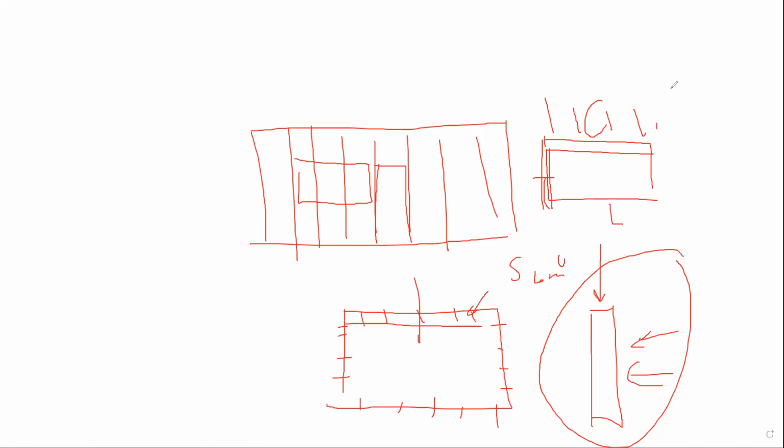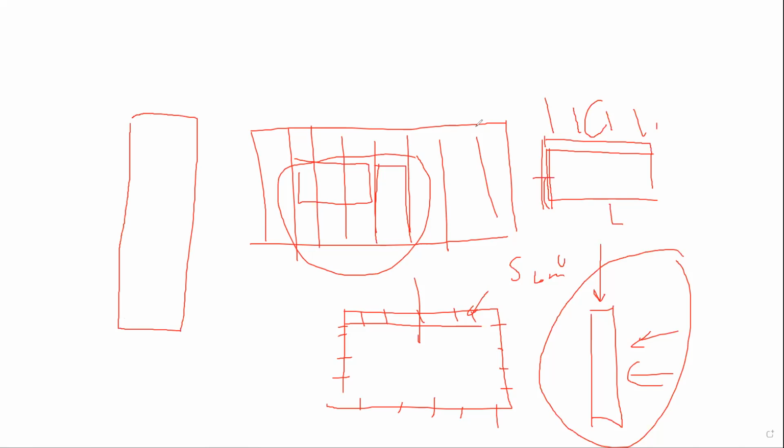So do you understand what that sketch is all about? It's a continuation of the design of an exterior wall where you have openings in the walls. Is that clear now? Yes, thank you so much. You're welcome. But for now, just design the exterior walls. And like I said, Rena, we normally use 2x6s because we want to create the cavity. And we normally start the spacing at 600, or 610 if you're doing imperial, because it's 24 inches.